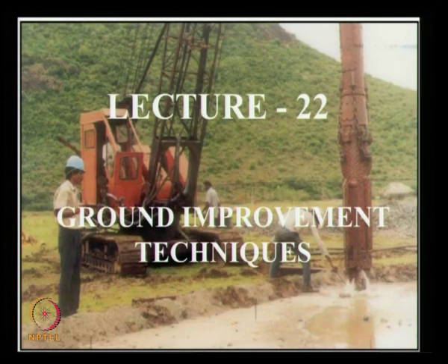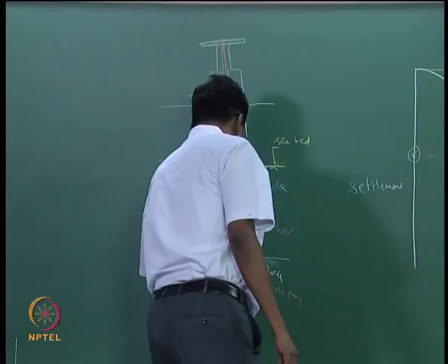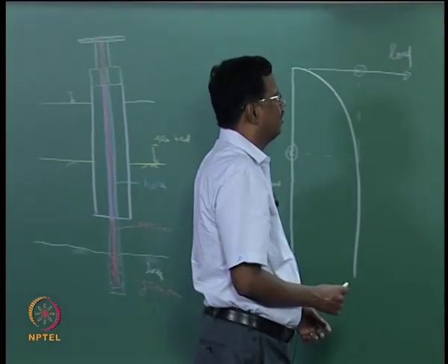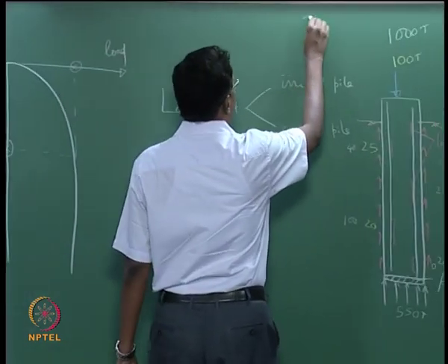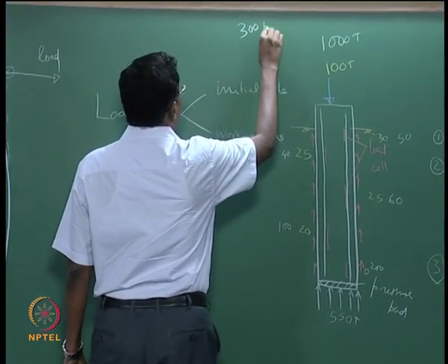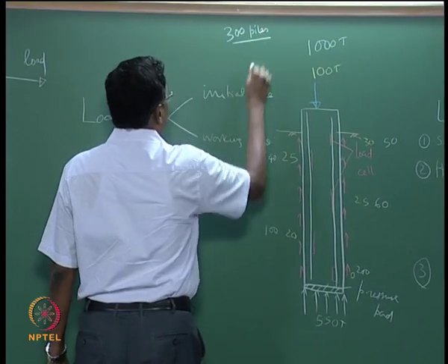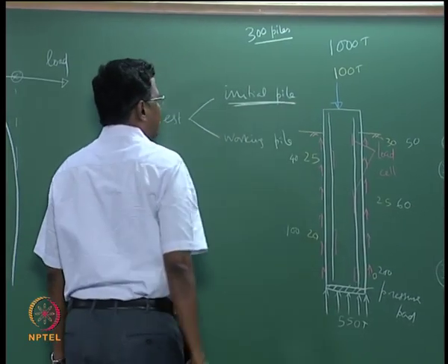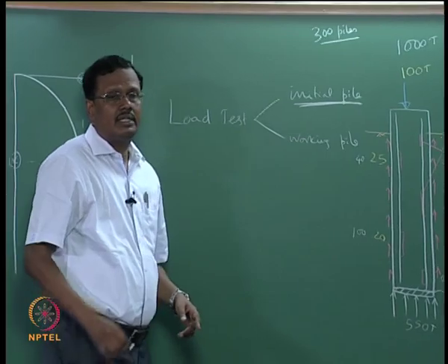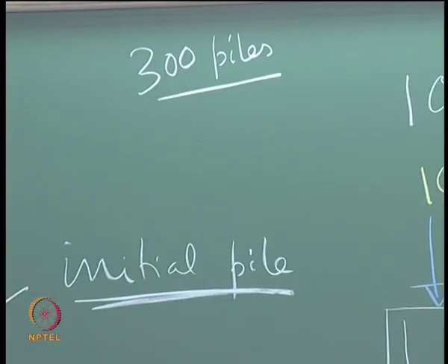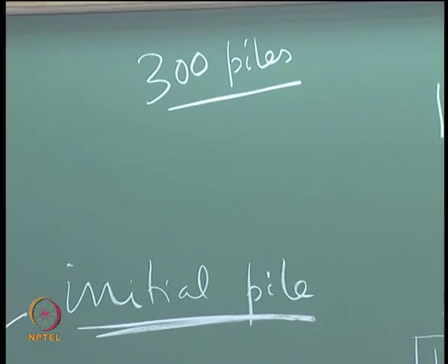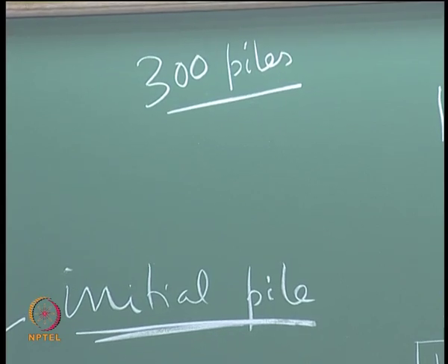So another important aspect is this initial pile load test. Suppose there are about 300 piles you have to do. It is preferable that the initial pile load test is done before starting the 300 piles. You cast it separately, do the test separately and then do it.